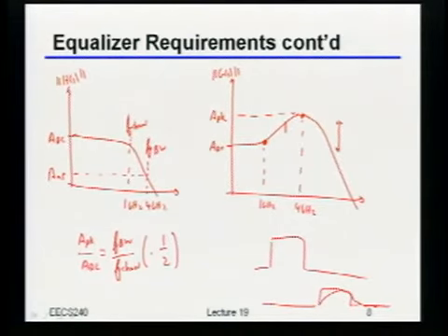So now, just to be really clear, what would have happened if this channel right here was actually a second order low pass filter with both poles at F channel? How would this ratio have scaled then? Yeah, it's squared. It would have then been that you need F bandwidth over F channel squared. So in other words, if I start adding more and more poles over here, it gets more and more painful to go up to higher and higher frequencies, because you have to create these really, really big peaking ratios. Okay? Does this kind of make sense to everybody?